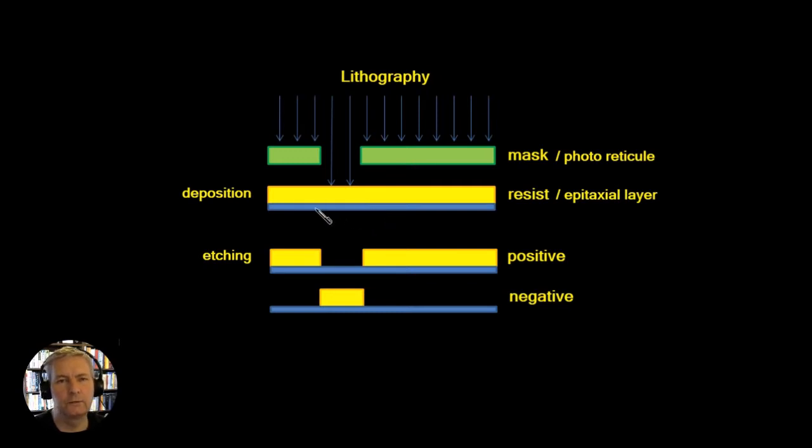So the first category we're going to look at is what we can do on top of the silicon wafer. And first of all, we're going to look at a process called lithography. Now, in order to ensure that we have only a particular region of the wafer active to us, we need some way of defining set regions of the wafer. And we do that using photolithography, or what is shortened here to lithography.